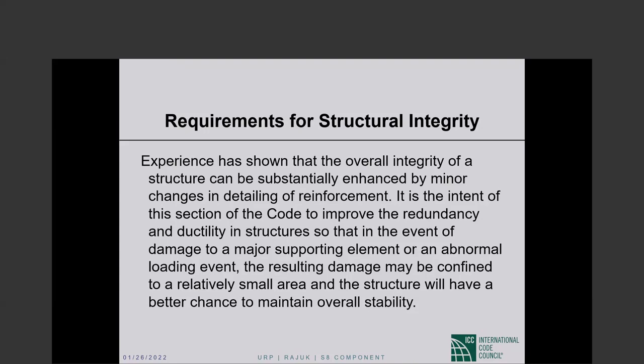The spacing between longitudinal bars and so forth is what I was talking about. The spacing of the transverse reinforcement, this is where requirements are relaxed from what they are for the columns of the superstructure. Now, if you are talking Dhaka, it is design category C or D. Newer parts of Dhaka, it is design category D.